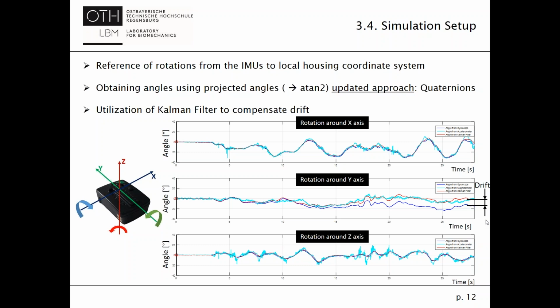And as the magnetometer is rather imprecise, 2 angles are computed by using the accelerometer. But those curves or those angles have a noisy trend, and so we use a Kalman filter for obtaining angles that have no drift and are not noisy.